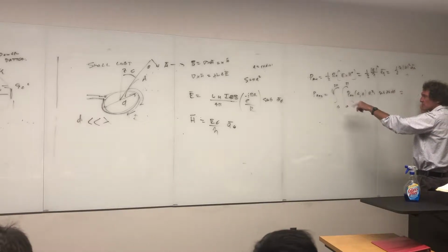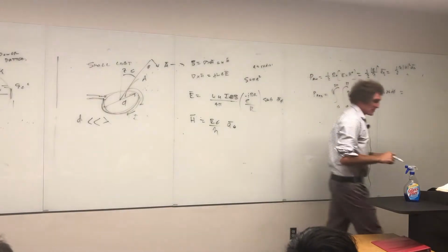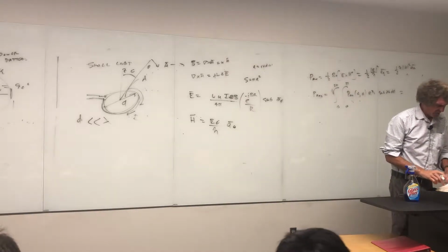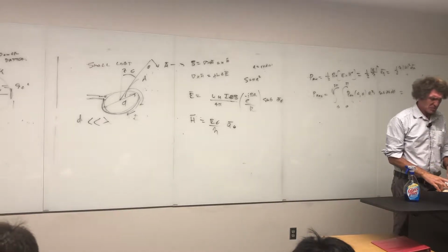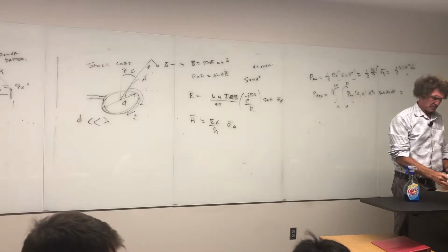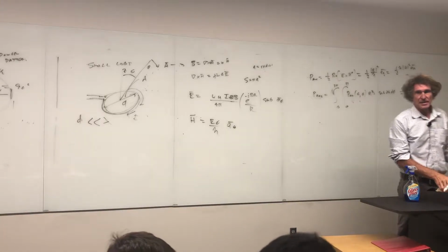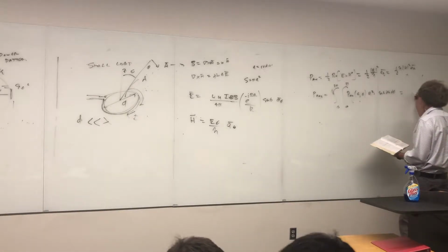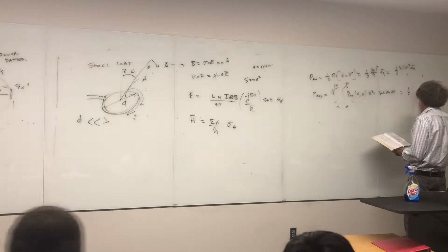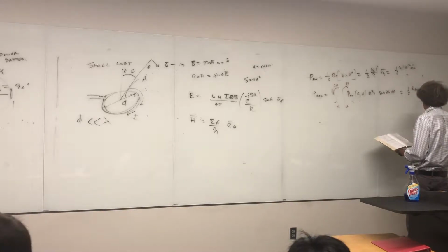This whole thing comes down to something when you do it. For P, radiation resistance, oh, I forgot the terms he puts down. I got my book too. In his book, he does it a little different than I'm used to seeing. He's going to say this is equal to 1/2 times R_rad, the radiation resistance, times I_0 squared.